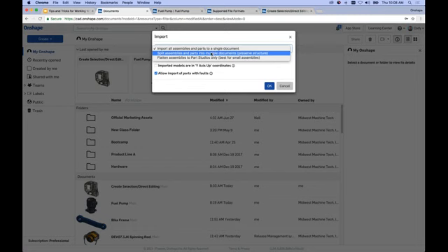The last one, flatten assembly, is very useful if you want to simplify something. So say, for instance, you're importing a model and it's a circuit board, and you really just need the geometry. You don't need all the complicated 100 parts that come with the assembly. You just want to simplify it and then bring it into your model. Flatten is a good use for that because it simplifies the geometry down to a single part studio where you can Boolean merge everything together very easily. But flatten is very useful in that circumstance where maybe I'm trying to simplify a model before I bring it into mine. I don't care about having every single part in the assembly level.